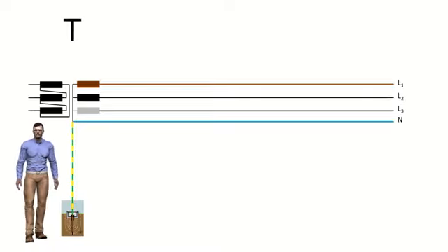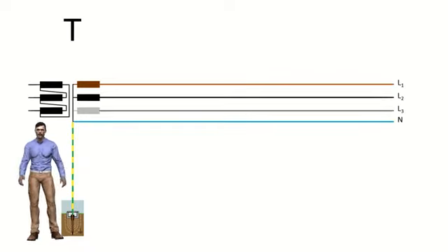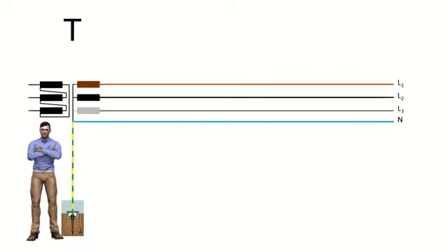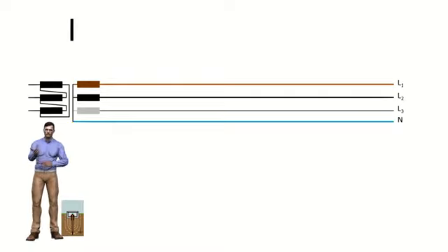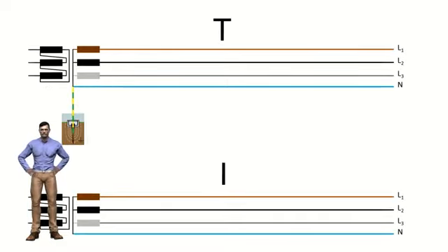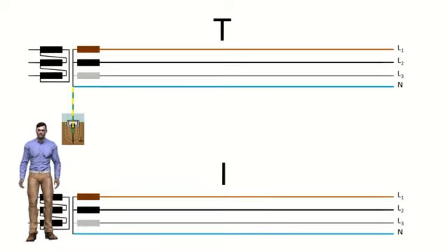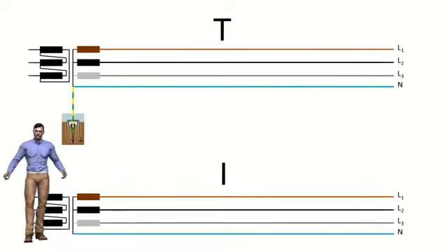We use the letter T, if there is a direct connection to earth in the transformation center, normally the neutral tap of the transformer. We use the letter I, if the active parts of the installation are isolated from ground, or if there is a connection point through a high impedance. Therefore, T, if the power supply is grounded directly, and on the other hand, I, if it is connected with an impedance or isolated, that is, an infinite impedance. With this word game you can easily remember it.